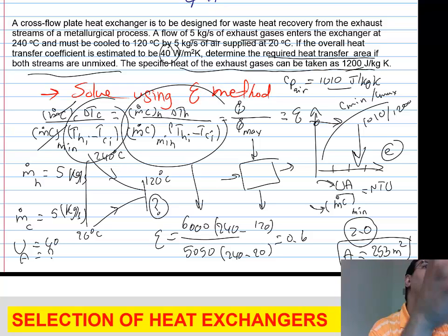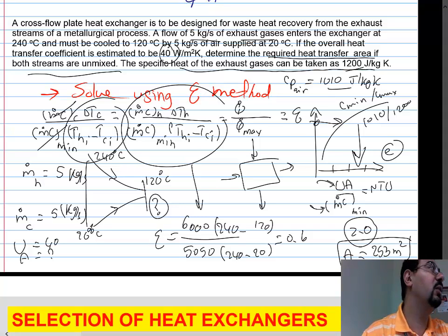Right, so the CP of air is from our textbook, from the table at the back for the air. So that's a good question. And so you know that if we do it at 20, that's probably not a good idea, right? Why is it not a good idea at 20? Because you know the air will get hotter. You don't know how hot it will get yet, but you know it will get hotter.